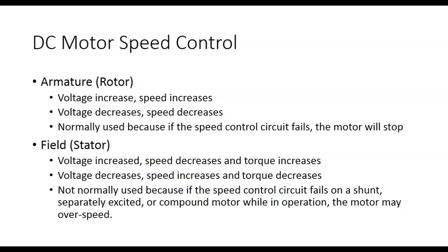So whether you understand it or not, it works on something called counter EMF, and you'll get into that if you take motor controls on what this thing actually does. The normal way to reverse these is to reverse the armature. That's industry standard, because on some of these you want to do it the same way every time, right? You understand that? And that way you don't have to guess. The problem we have is that if you lose the field circuit on a shunt or separately excited or a compound motor, them suckers can run away and they will sling themselves apart.